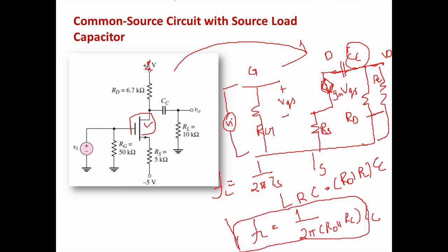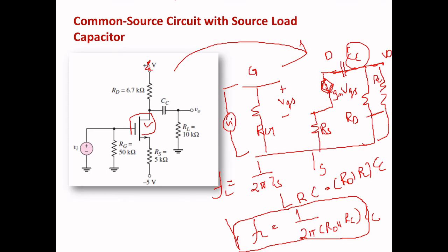So this is the formula for lower cutoff frequency. Okay, so we can put your voltage gain also, right? When you calculate the VA, just apply the KVL in this loop. Already I explained you. So VI equals VGS plus gm VGS into RS. So this part alone I will draw here, so you will not be confused.